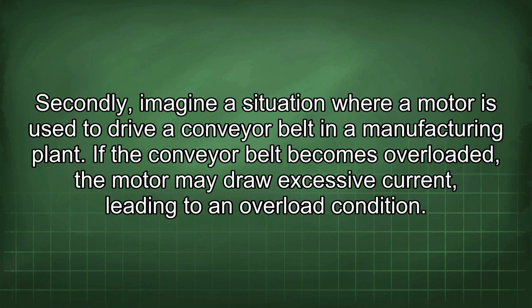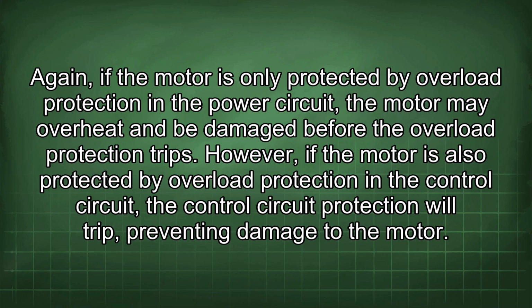the motor. Secondly, imagine a situation where a motor is used to drive a conveyor belt in a manufacturing plant. If the conveyor belt becomes overloaded, the motor may draw excessive current, leading to an overload condition. Again, if the motor is only protected by overload protection in the power circuit, the motor may overheat and be damaged before the overload protection trips. However, if the motor is also protected by overload protection in the control circuit, the protection will trip, preventing damage to